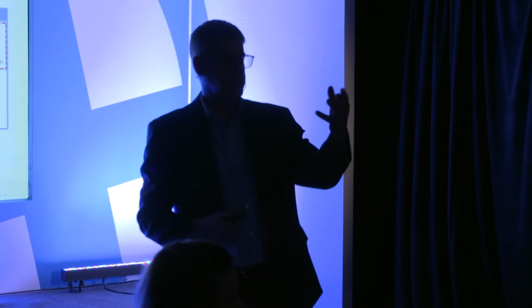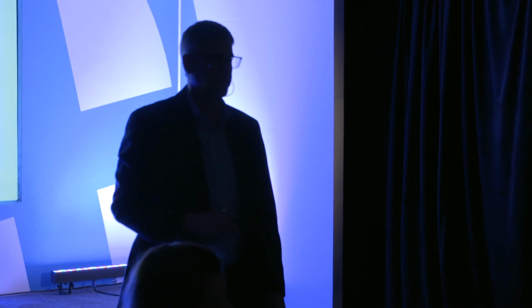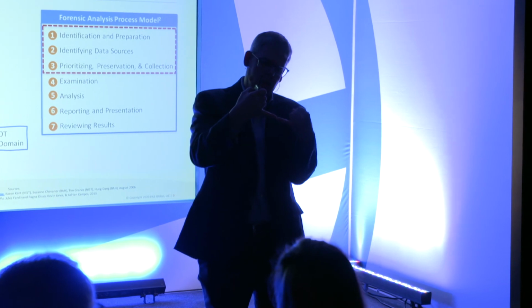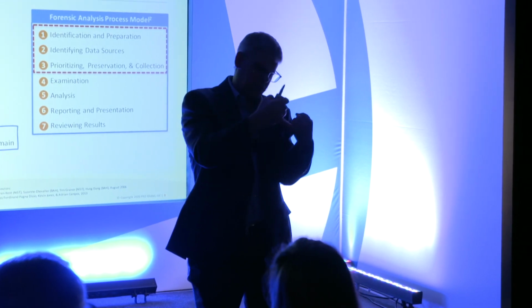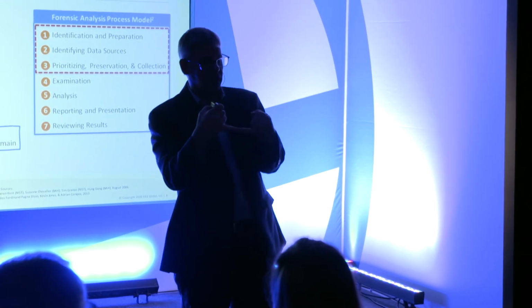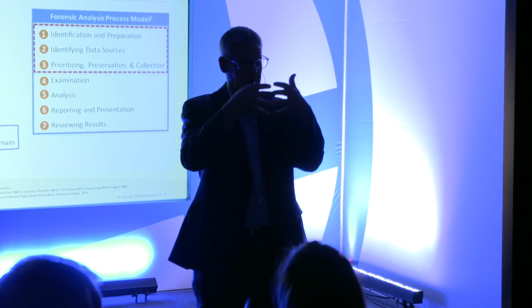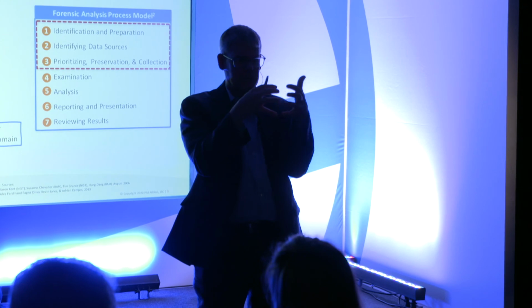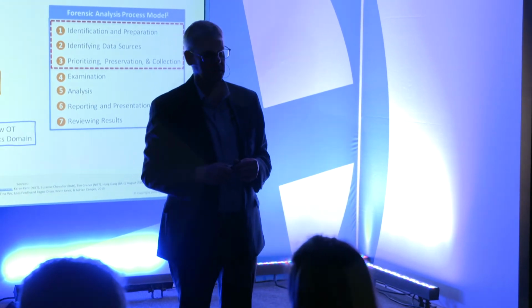Man, you are just doing my pitch right now. This is awesome. So yes, part of that as well is, hey, wait a minute here. These two things are talking together, but this says it's gallons per hour. This says gallons per minute. That's not right. So that type of validation, because we know the properties that have to line up, that have different names in different devices. So we normalize this and do that type of data validation.